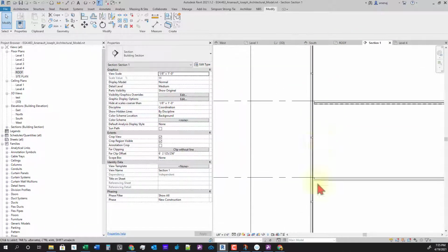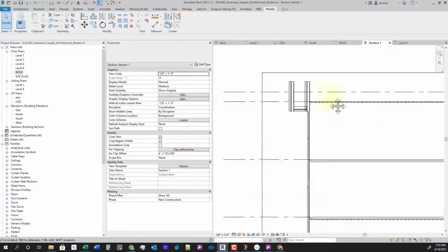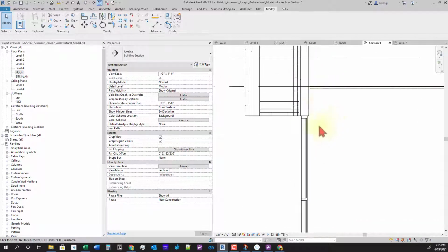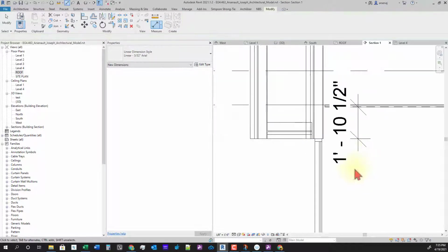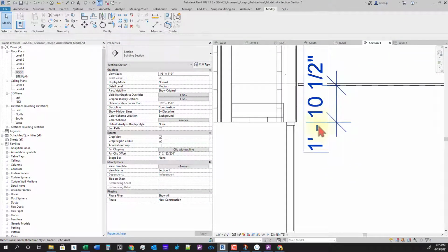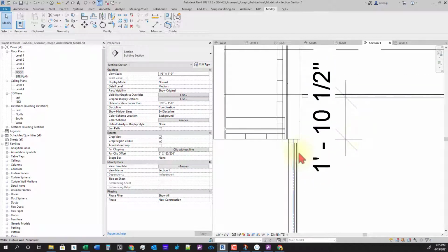This can actually be just a 6-inch metal stud wall. And actually, I think depending on the depth of our beam, it should be 2 feet-ish. Yeah. So we'll have our beam here, and we'll probably tie back our curtain wall.